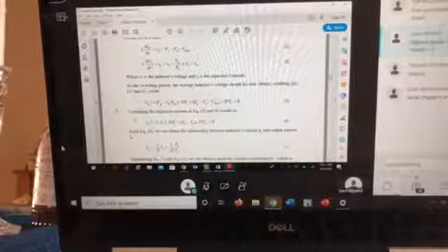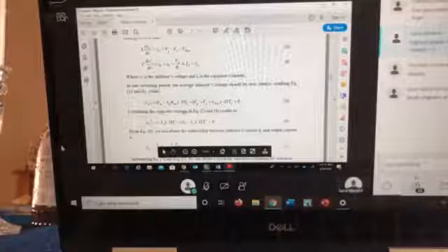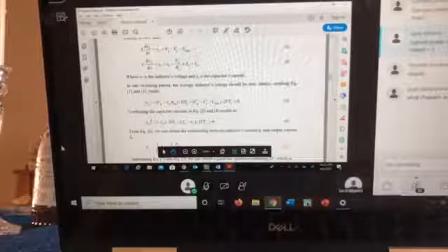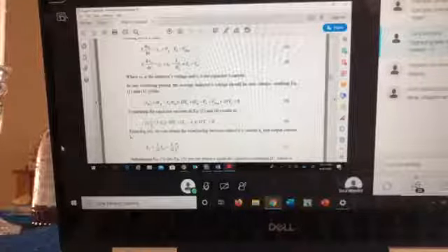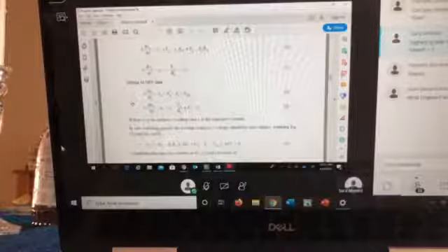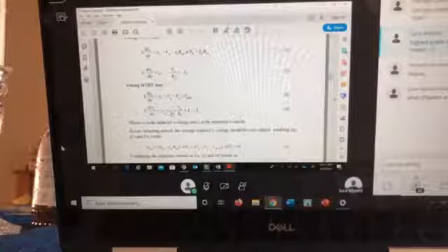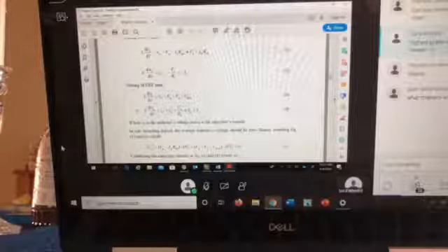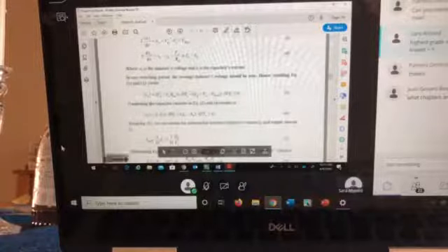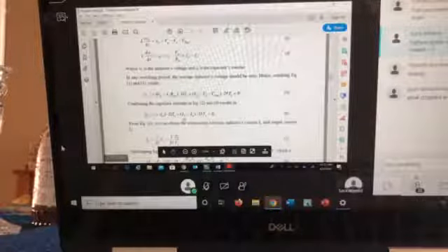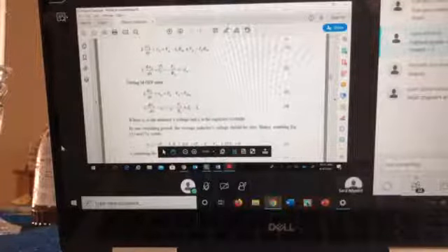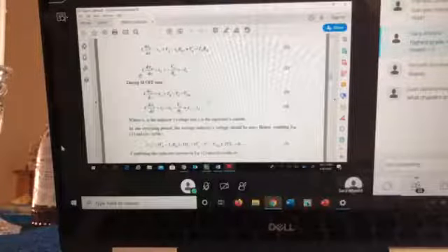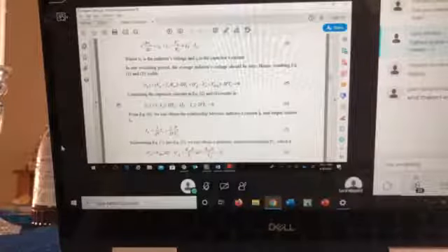And then my second equation, that will get me the inductor current, is the capacitor current. The average of the capacitor current for one cycle is equal to 0, which means I have equation number 2 and equation number 4 here. This one multiplies by dTs and this multiplies by d prime Ts. And then from those two, I can get what is I of L. Okay? So again, you see how the formatting is? I'm writing each equation, I'm numbering the equations, and it's clear and easy to follow and read. Helping you and helping us as well, and also learning how to write a report.